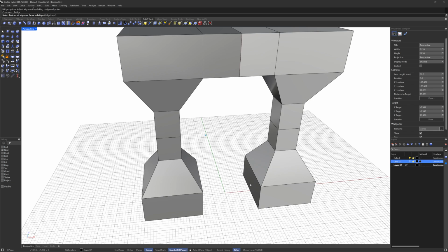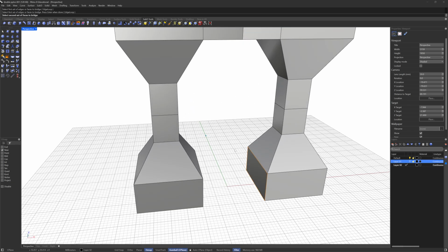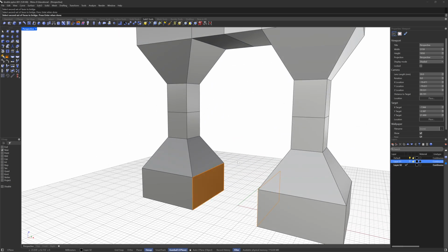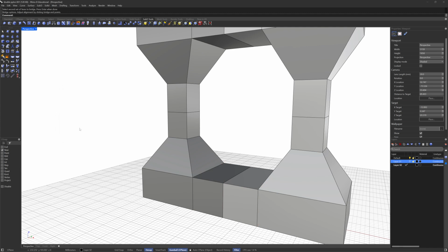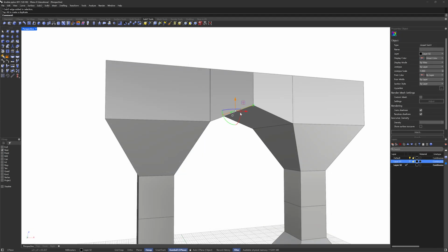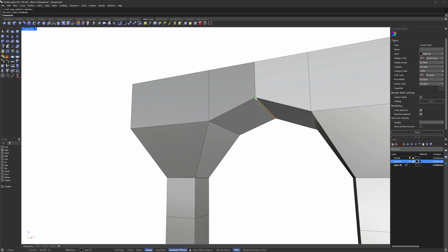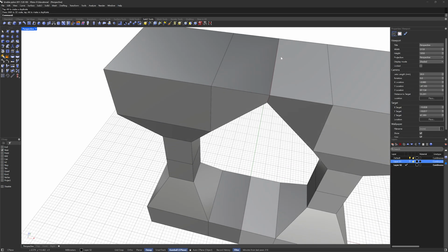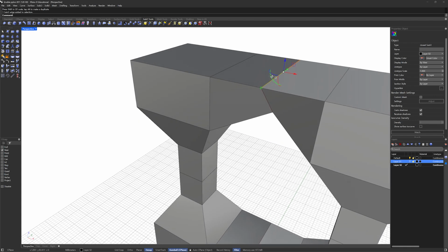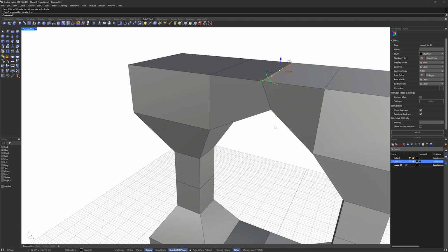And let's do the same thing on the bottom. So right click to repeat, face, right click, opposite face, right click. And these are all the same numbers. So I'm going to move this part up. Notice I just pick an edge and that's up in the air. And we can also scale it in. So that works pretty good. Probably want to scale the top too. So I'm just picking that edge. You gotta be sure you don't get the other one still selected. So I'm gonna bring those guys in.